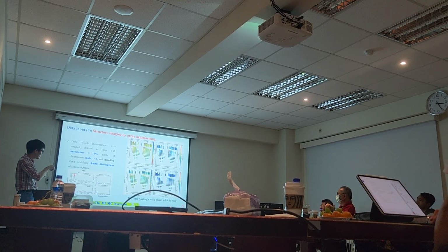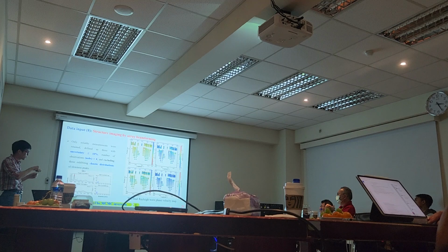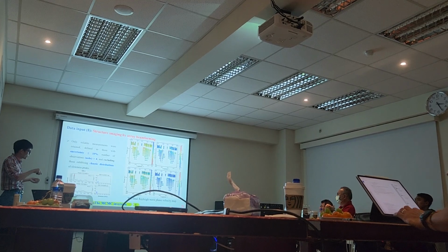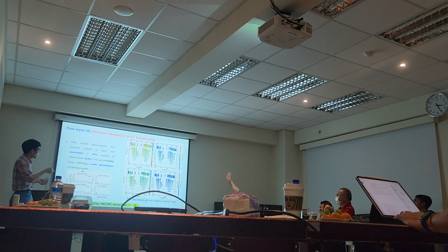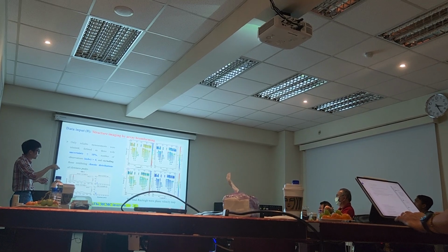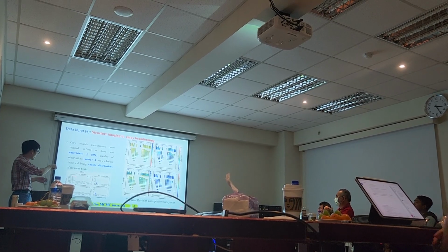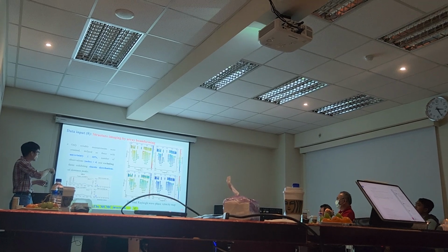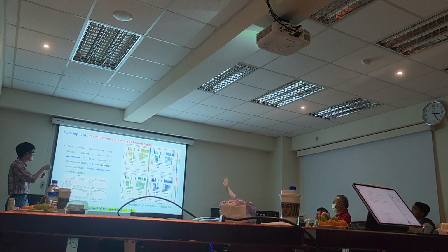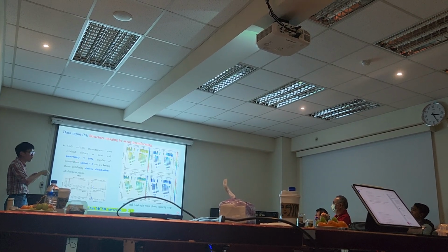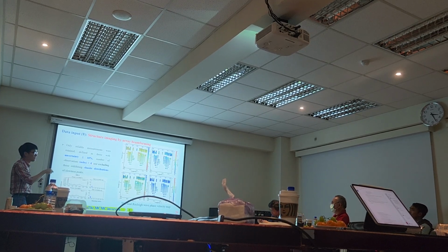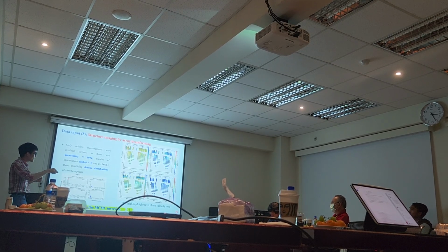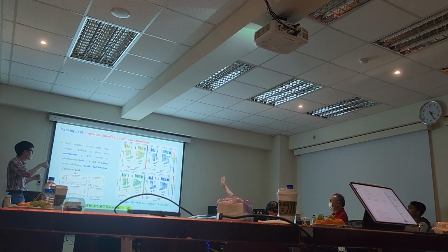We have a peak distribution like this, and we define consistency and good distribution. Also from the number of measurements and the standard deviation of this distribution, we use some criteria to remove unreliable data: uncertainty less than 10%, and the number of observations should be larger than 4.